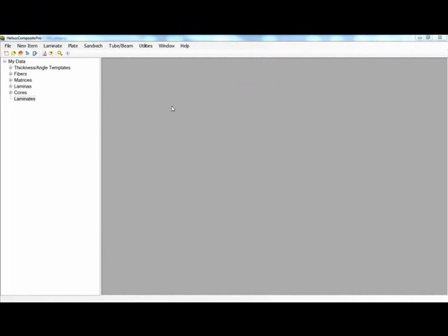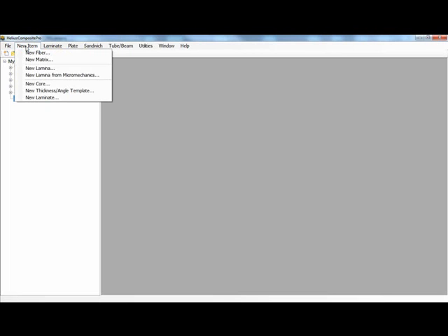In this video, I will demonstrate how to use CompositePro to support a finite element analysis of a composite structure. Oftentimes as engineers we don't have lamina or ply level material data sets, and we have from a manufacturer a fiber material data set and a bulk resin material data set. So we can use CompositePro to arrive at ply level or a lamina data set using the new lamina from Micromechanics tool.